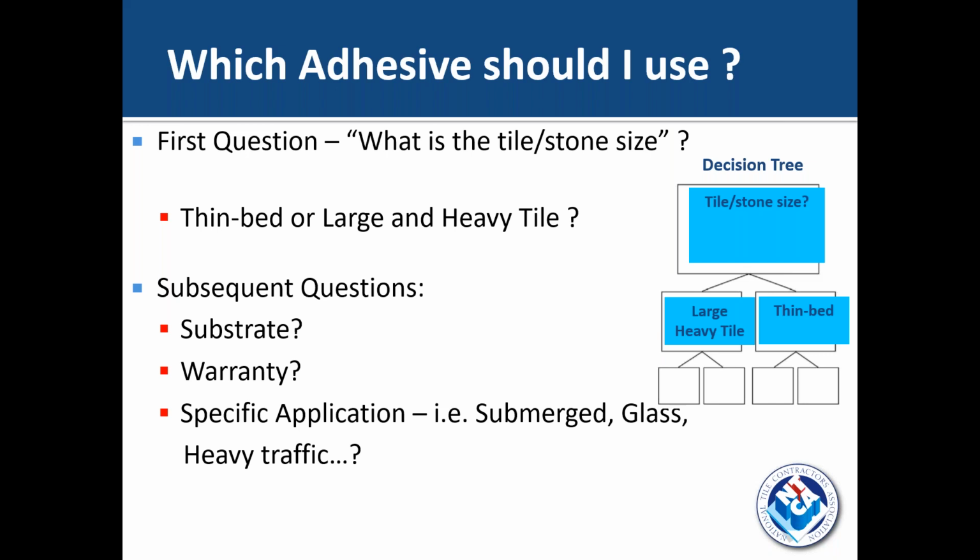When bonding gauged porcelain panels, is there an additional curing time that you have to consider? It is longer. Again, I would also consult with that tile manufacturer. Yeah, I would go both ways on that, Jonathan: the tile manufacturer and the setting material manufacturer.